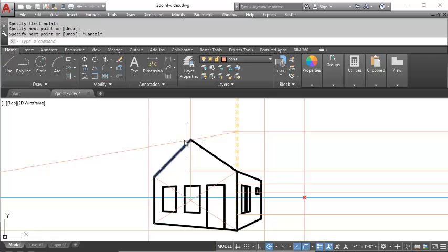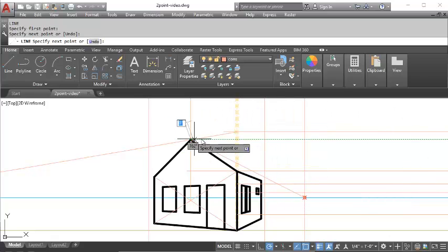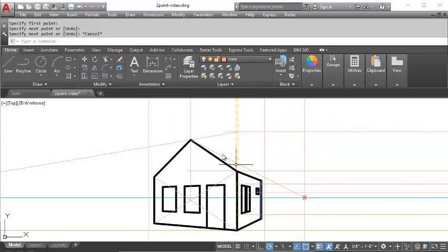Now I don't really know where this edge is in space, but I do know that if we're looking at the roof from the position we are, we're going to be able to see the underside of where the two rafters come together and stick out here, and I know that it's going to follow the ridge line of this roof. So I will draw as a construction line the ridge of the roof, as the ridge would be parallel with the wall, so it would follow the same vanishing point.